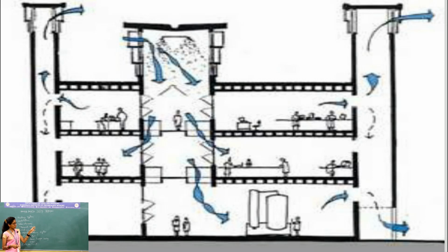So these wind catchers will be catching the air, directing the wind into that area, and then the wet cellulosic pad will absorb the heat and provide coolness to your hot air, and that will be drawn down due to the variation in density, as the density is going to increase.